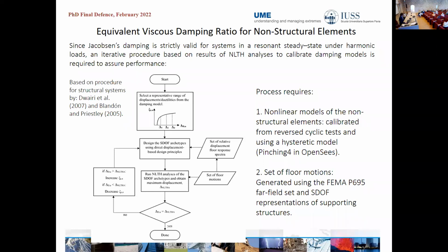If the displacements are not the same, we can change the value of the equivalent viscous damping and repeat the whole process until we get a similar relationship between the target displacement and the displacement from time history analysis.